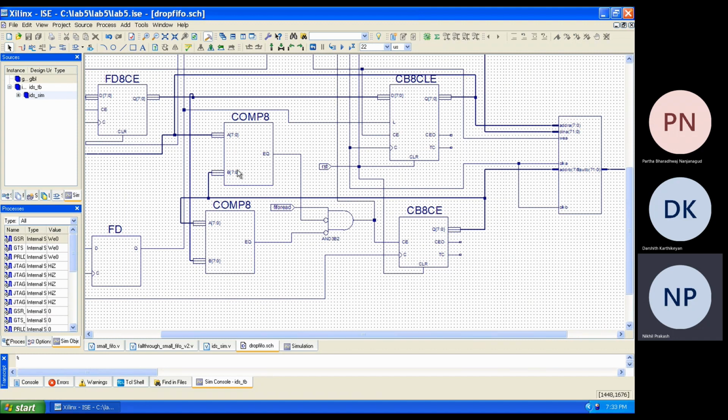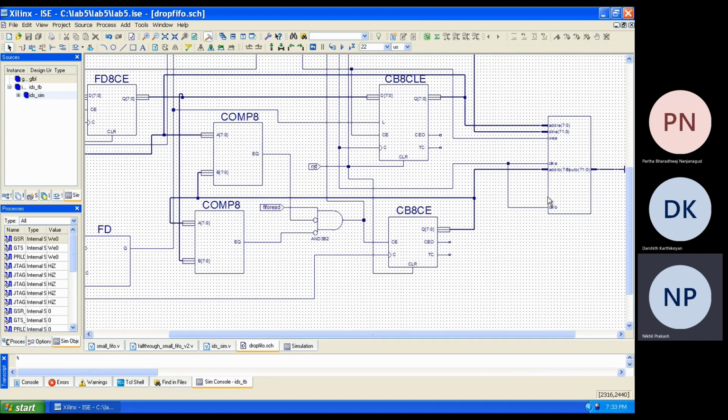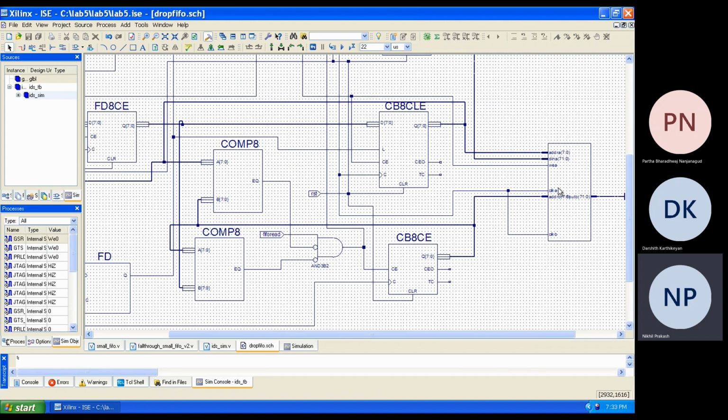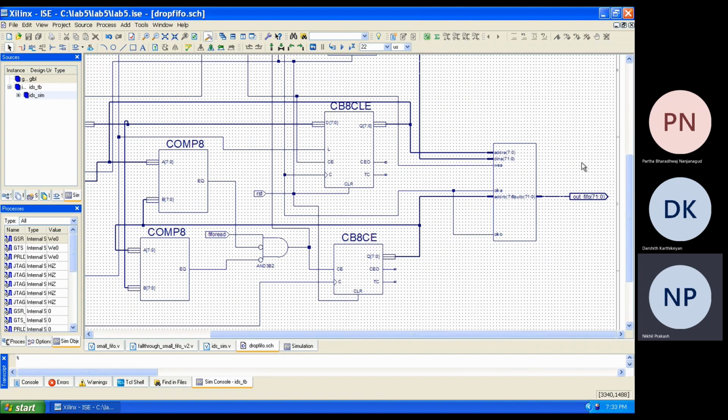What essentially that says is that you're not allowed to read. So let's say I've written 20 words already in a data packet. Until we check that the pattern is not there in all 20 of them, only then are we allowing you to read packet 0, packet 1, packet 2, and then till packet 20. So my read pointer will not increment until it checks that all the words in that packet do not have the pattern. Only then the read pointer increments, and you get the output.